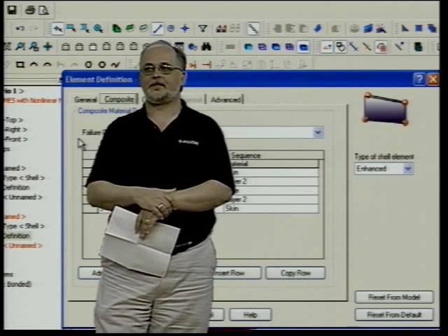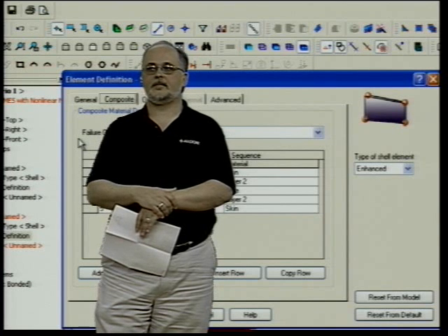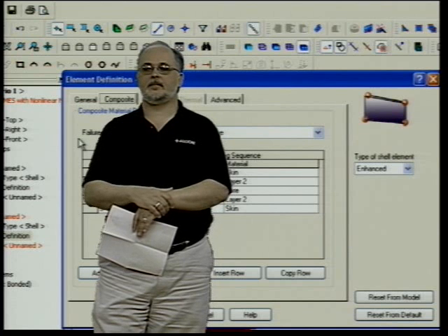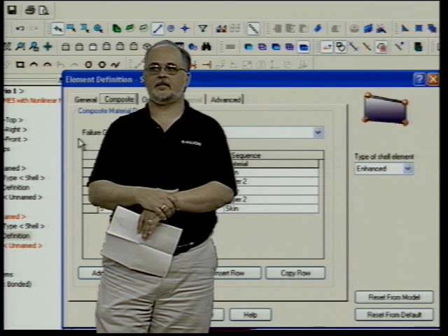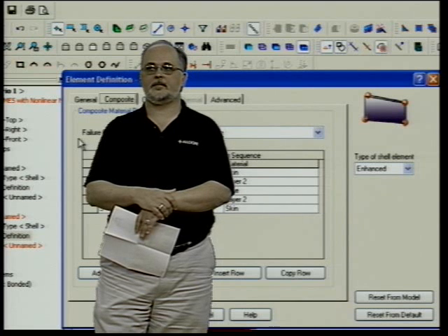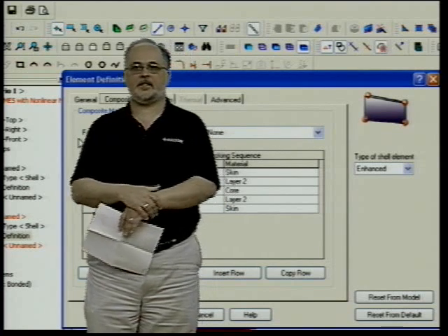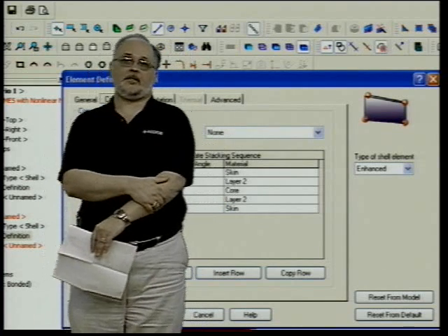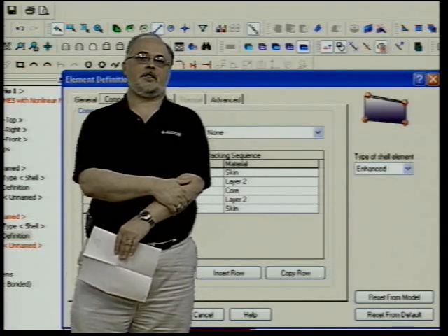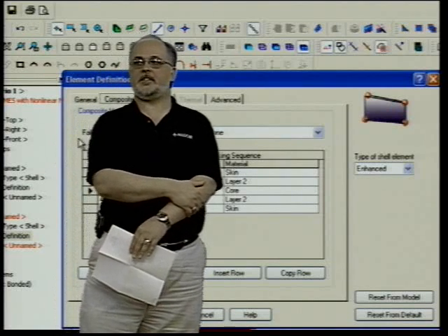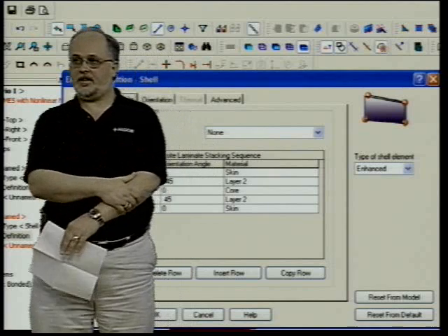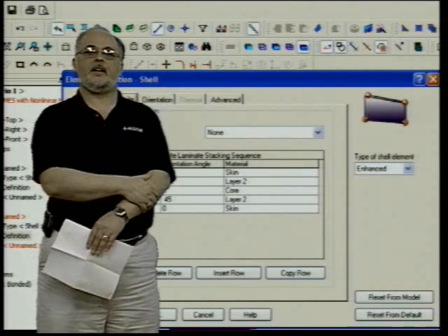You can do a sub-model of a 1 inch by 1 inch, do a lot of analysis on it, study the behavior, and say, okay, well, this seems to be behaving as orthotropic, I'm going to build my model using these kind of derived properties from my small model. Right. That's a very good example. Yeah, and that'll cut down your final model size to something manageable, without millions of elements in it that might be needed for something as complex as a honeycomb shape.